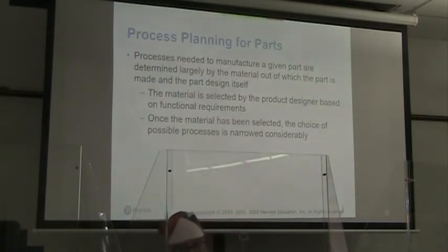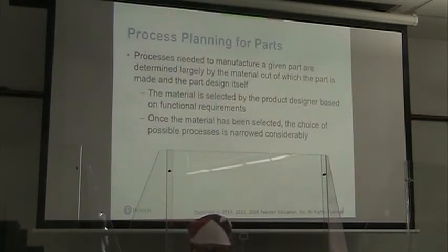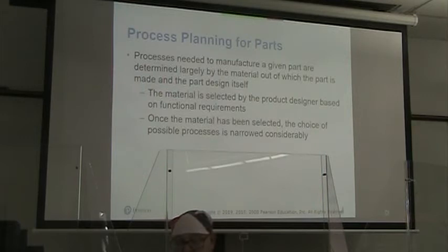So anytime it looks like it's going to be very hard to make processes that will fulfill the design, we need to go back to the designer and say, all right, does it really need to be like this? Does it have to be titanium, or would ordinary steel do? Do we really have to have tolerances that are to the micrometer, etc.?